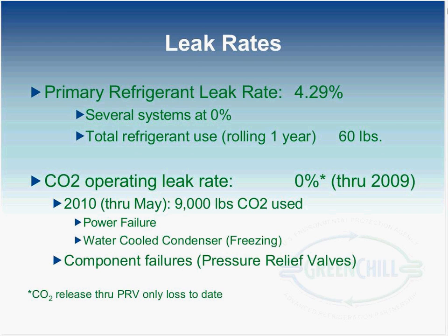With another store, we had a water-cooled condenser in one of our southern regions. Unprecedented cold weather froze the plumbing lines. We didn't take the correct precautions to heat those lines, and because of high head pressures, because of the high cycle not working properly, we lost a charge there. Without those 2 losses, we are still seeing a 0%, what I would consider a traditional leak rate.